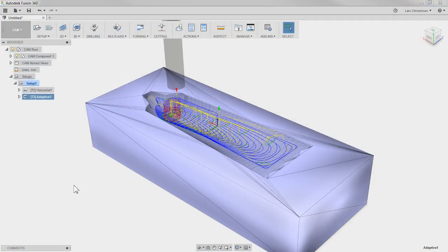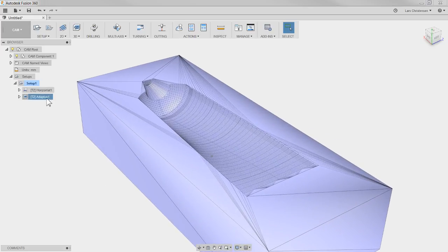Think of silhouette in the selection as almost like shining a lamp down from the top. Anything the lamp hits something on, that would be a silhouette. So the default machine everything is kind of like seeing everything. But since we put the tool to be inside that boundary, it will never work on its way out. So here we've got a nice little roughing toolpath.